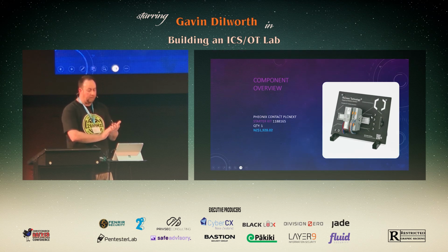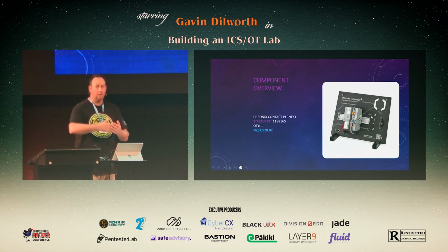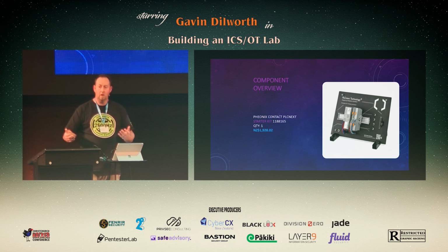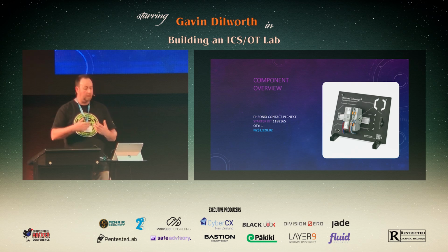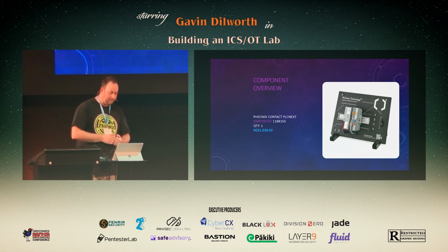But basically when you buy your PLC, you have to then go through and ask, do I have the right cards for digital and analog? Do the instruments match? Are they compatible? Are they on the same voltage? Do they understand each other? And so there's this massive process of trying to make sure that that is correct before you even purchase it. If you get that wrong, then it's going to cost you a lot of money.